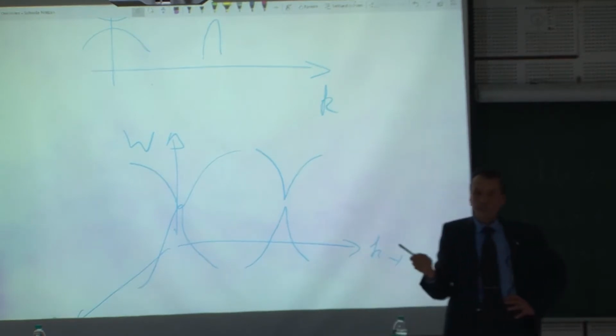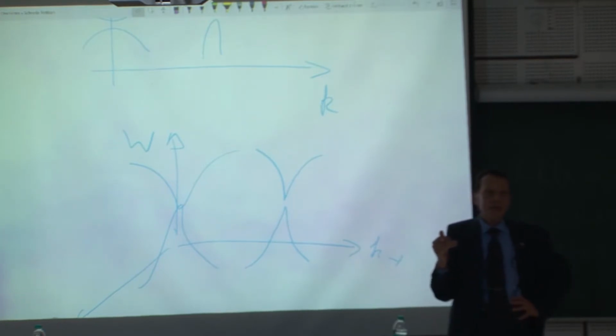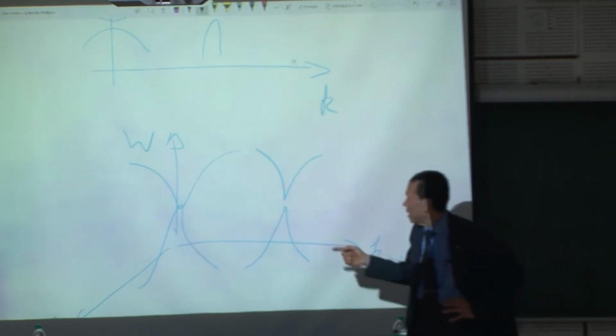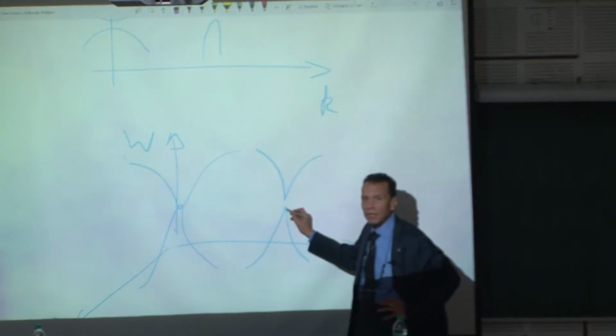And this is actually the hope of solving terahertz, because if I use graphene in my transistor, till now the technology is not so mature. But as you see here, we have now structures in which you can achieve, not necessarily infinite, which is the theoretical limit, but you can achieve very, very low effective mass. So actually nearly zero. And what does this mean? I have high mobility electrons or high mobility holes.